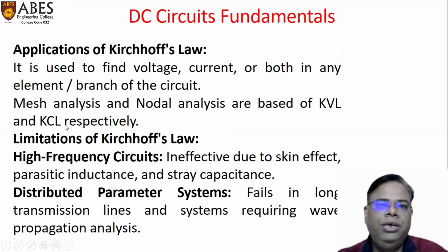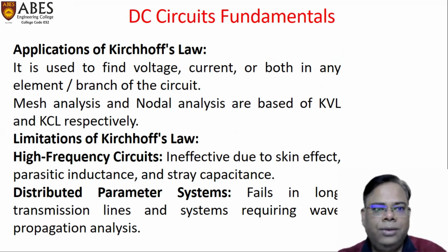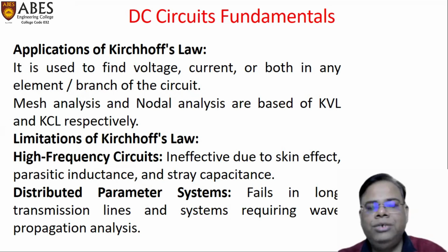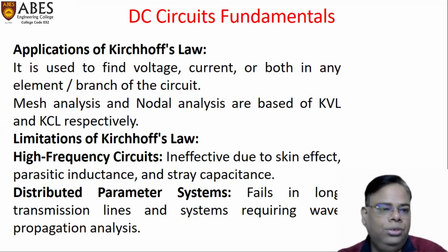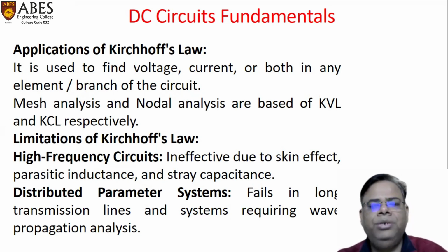If we talk about the applications of Kirchhoff's law, it is used to find voltage or current or both in any element or branch of the circuit. With the help of Kirchhoff's law, we can find voltage and current in any branch of the circuit. Another application is mesh analysis, which is based on Kirchhoff's voltage law, while nodal analysis is based on Kirchhoff's current law. The main limitations of Kirchhoff's law are that it cannot be used for high frequency circuits and it also cannot be used for distributed parameter systems.